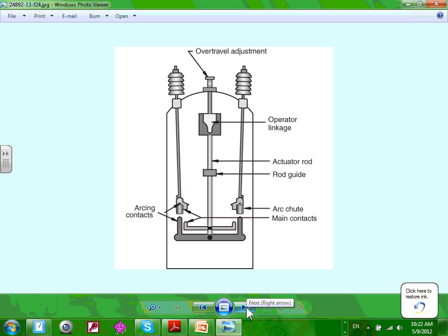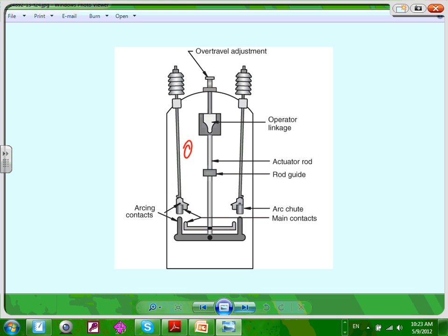Okay, moving into the medium voltage, this is called a dead tank oil circuit breaker. Now we elevated this one into oil. We're putting oil here. Anybody know why we put oil? Now we interrupt in oil. Can you guys see here's where my arc shoots. Where are my contacts? There's the actuator, operator, link. So now we have to monitor the oil.